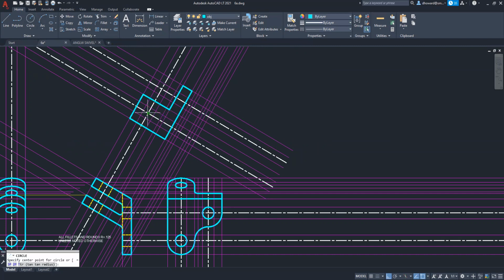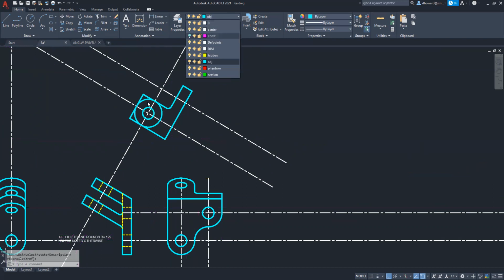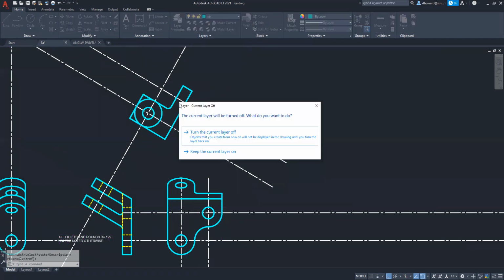So the hole is just going to be from the center to any one of those edges, and the radius is just going to be, again, the center to any one of those edges, and then we'll just trim off those pieces. And then the fillet here is just a standard true size fillet. So F, enter, R, enter. And remember that one was slightly larger than our default of 0.125. It was 3/16, which is 0.188. Or you can type in 3/16 and grab those two lines. Okay. I'm going to turn off my construction lines for a moment, trim this out, trim this stuff away.